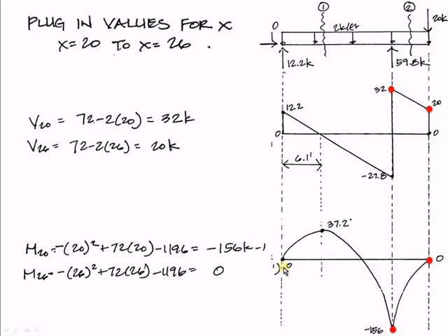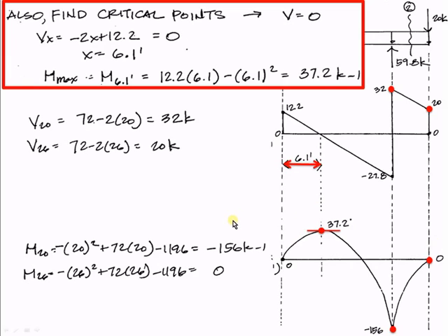But what we still haven't determined, although it's shown here, this is the answer, is all that we know are just these points. For the shear diagram, we know that it's linear, so maybe we're done with this, though we haven't solved for this yet. We know these are concave down formulas, but we don't know exactly where they go. How do we know what they are? So what's important to figure out critical values is we're going to look at locations on the shear diagram where V is equal to 0. And we recognize, because this is a straight line, that there is some 0 point there.